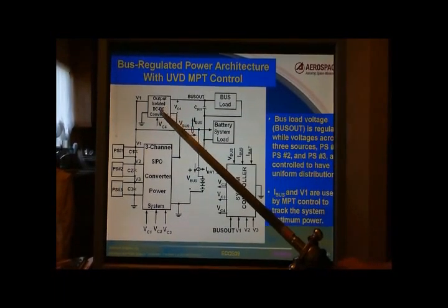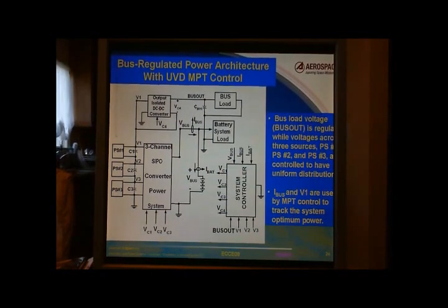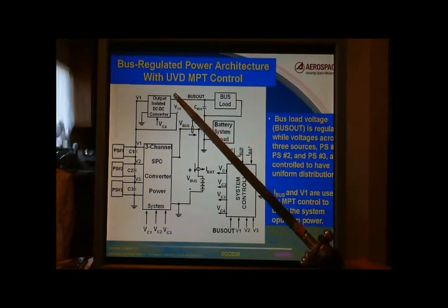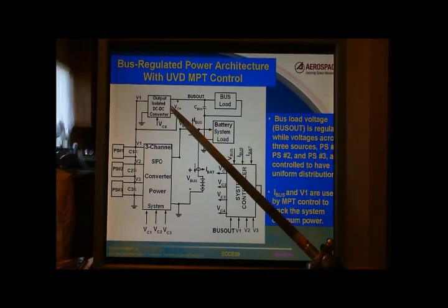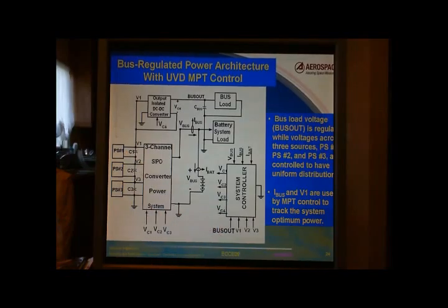The DC converter can have a modest efficiency such as 85%, but the power conversion from the total sourcing voltage to Bus Out can be as high as 95%, depending on the amount of the voltage VO4. The smaller the VO4 with respect to the total sourcing V1 voltage, the better the power conversion efficiency.